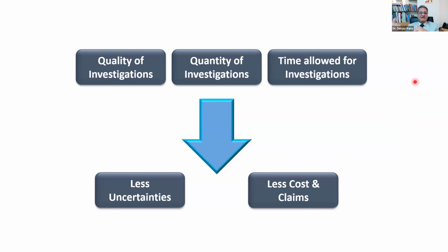And this is a very good statistic on challenges of underground. It is from ITA, the International Tunneling Association. So these statistics I have not made up. It says even a comprehensive exploration program recovers a relatively minuscule drill core volume that is less than 0.0005% of the future excavated volume of the tunnel. There is a basis for this sampling level: 100-meter diameter borehole up to 100 meters in a 5-meter diameter tunnel, etc. But look at the number here, 0.0005%. That is the amount of information we are actually collecting for designing our project.